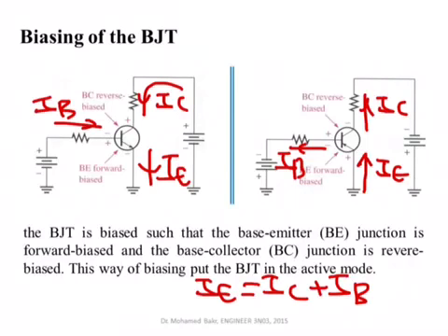So what's happening here: for an NPN transistor, you make the base more positive than the emitter, so this junction is forward biased, and this voltage here will be around 0.7. You make the collector more positive than the emitter, and because these are the same type of material, this is not a junction, so the voltage here can be any value really. And so this tries to push current here, and the value of the current flowing will depend on the bias being applied to the base. And the same thing is happening here.